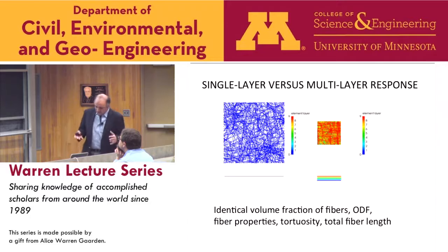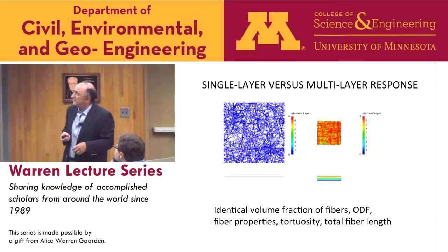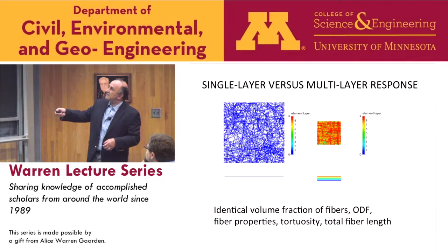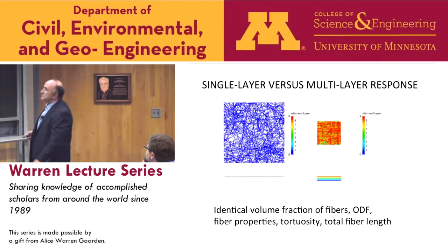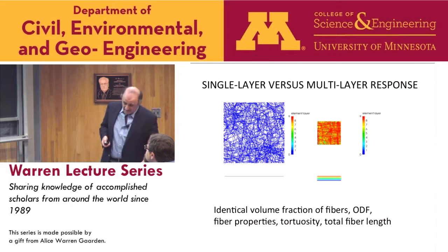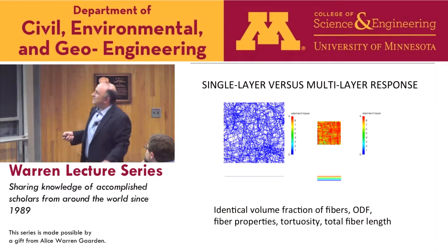Now, what this tells us immediately is the following. If I look at multi-layers, because the fibers from each layer are in contact with the fibers from adjacent layers, the distance between contacts in multi-layered structures is small. It's a factor of 2 or 3 roughly smaller than here, because here there are no additional contacts coming from the neighboring layers. If the distance between contacts is immaterial, but the fiber fraction matters, then you say, look, the bending deformation plays a role, because the bending deformation is very sensitive to the length of the beam. And that gave us this indication.